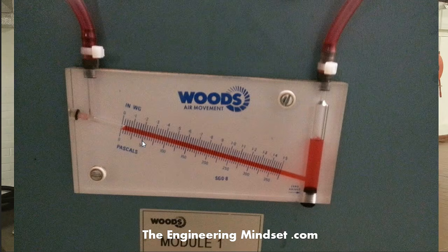A really good tip is to actually mark these, so put a sticker or draw a pen mark to display what a clean filter mark should be and where a dirty filter mark should be. That way, when your maintenance team does the walk rounds, you can go along and if it's dropped below, say it was at 150 pascals, if it's gone down to 200, the red dye, then you will know that you should have changed the panel or the filters by now, and then you can get the maintenance regime in place to do that.